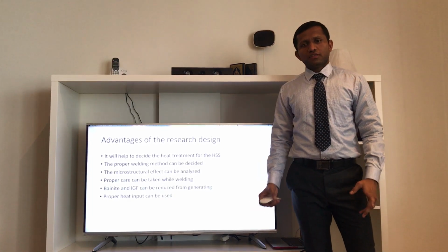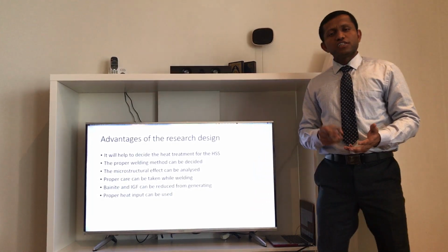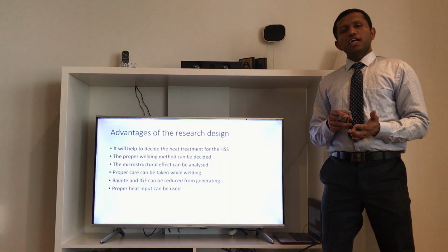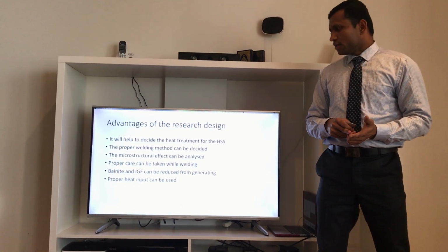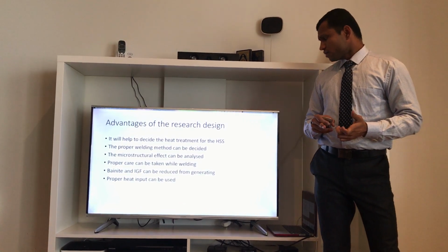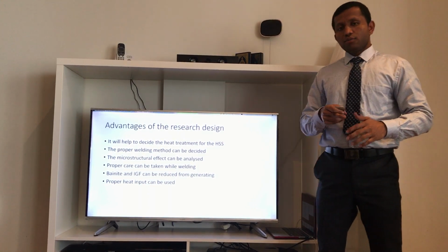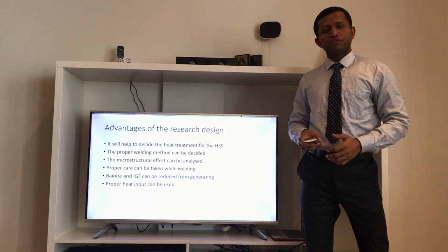Advantages of my research topic. So what are the advantages? It can suggest the heat treatment process for high strength steel. It can give you the proper welding method. It can give you the heat input method, and the generation of cracks can be reduced by giving the proper heat and by reducing the formation of bainite and intergranular ferrites.